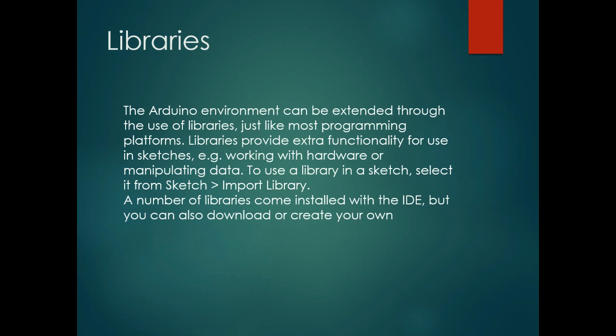Even Arduino has lots of inbuilt libraries. For example, when you use servo, you need to include a library called servo.h that takes all the things from the servo.h, and we can access any of the functions that we need to use in it. So you can make your own library, or download libraries from the net. If you want to import a library, go to Sketch. There will be an option called import library as a zip file.